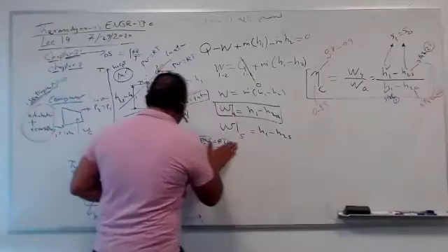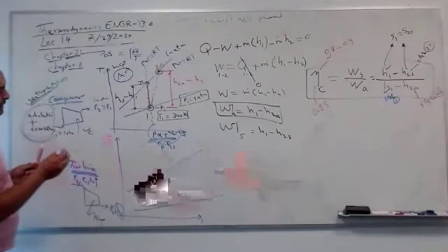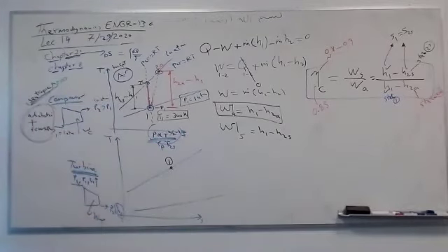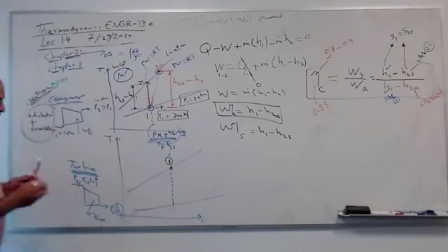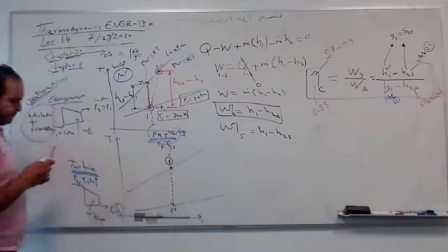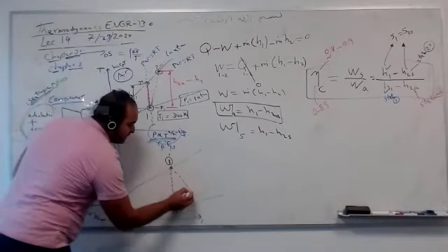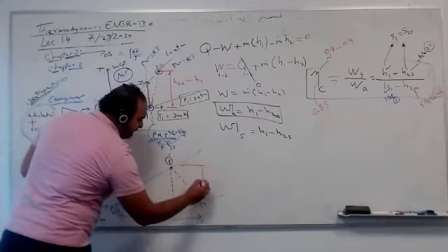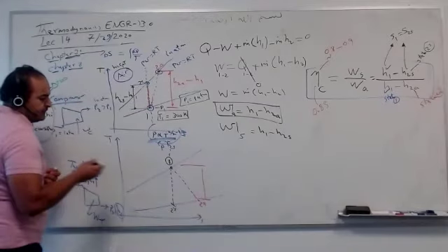Let's repeat the same thing we did for the turbine. Let's start with state 1. For the turbine, at state 1 it's high energy, high pressure. I'm going to expand it isentropically, adiabatically, and reversibly. So this is now 2S. But in reality I'm expanding with losses. It's 2A. So the vertical distance to 2A is shorter than the vertical distance to 2S.